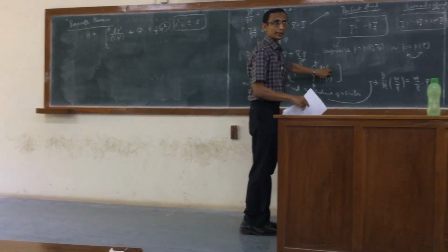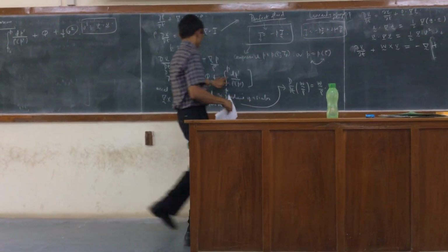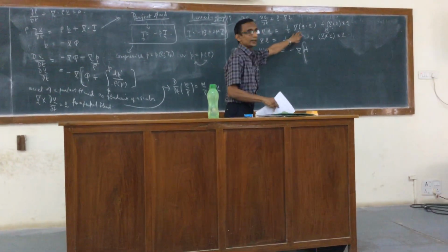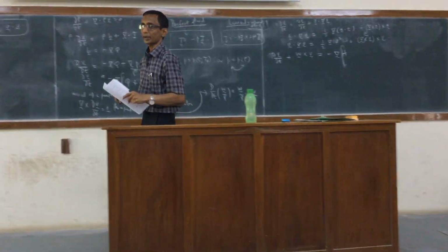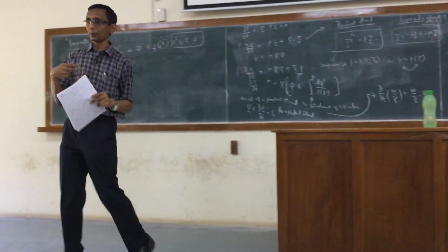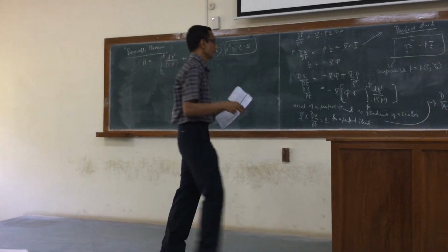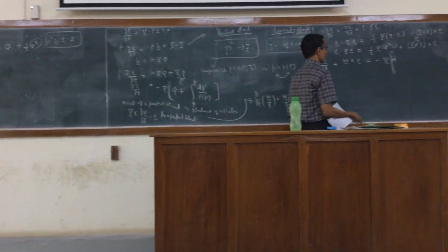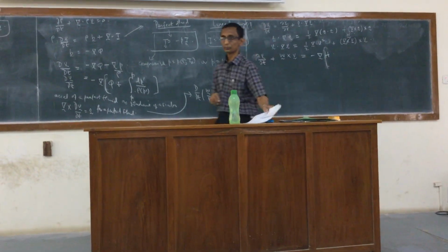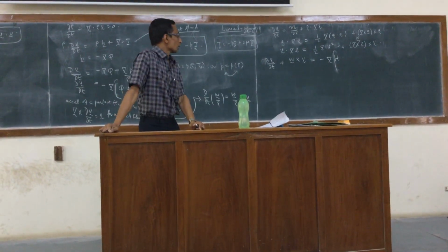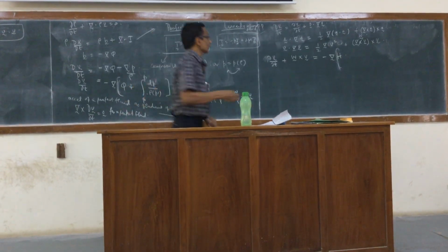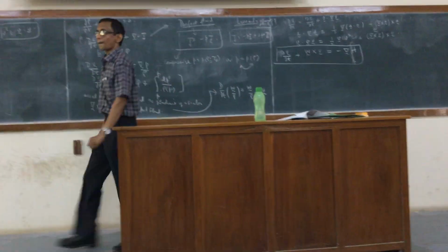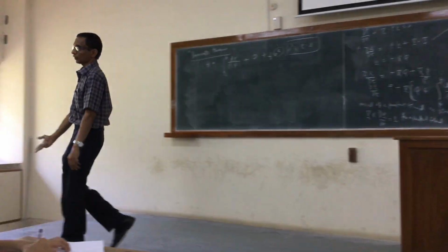Two terms of the h are already there on the right hand side here. The other term is coming from half times the gradient of v squared, right? And when it comes over here, it will become minus half times the gradient of v squared. So that can be taken into the minus of the gradient with a positive sign, and I will get minus the gradient of h. So this is the basic equation that will help us get the Bernoulli theorem. Now you can impose whatever condition you want.